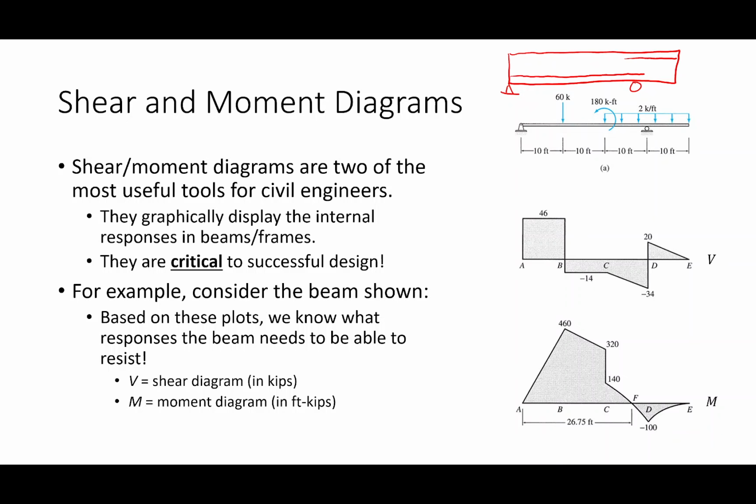This is the shear diagram, and it tells me where to place shear stirrups in the beam. The higher the shear, the more closely spaced those shear stirrups are. I can tell you exactly what the reinforcement diagram of this beam is going to look like, or not exactly, pretty close, just by looking at this. It's a very, very powerful tool. And being able to construct shear and moment diagrams from the free body, from the loads that are applied, is just a very fundamental skill.